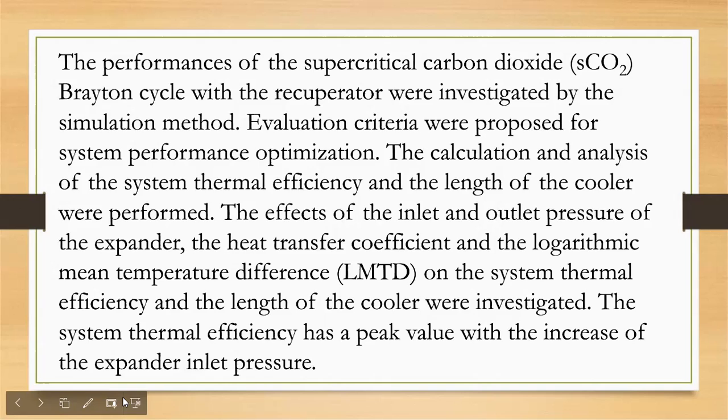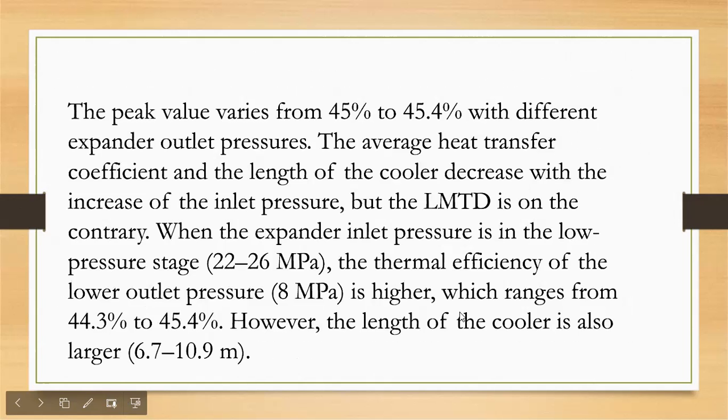Here the slide tells about the cooling area and pressure, and what the thermal efficiency is. Coming to this peak value, the peak value means the maximum value. The peak value varies from 45% to 45.4% with different expander inlet and outlet pressure. The average heat transfer coefficient and the length of the cooler decrease with increasing inlet pressure.